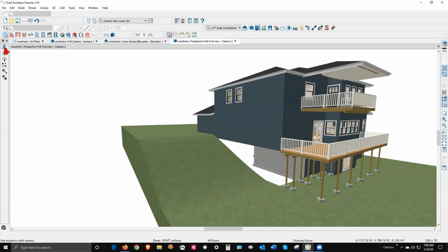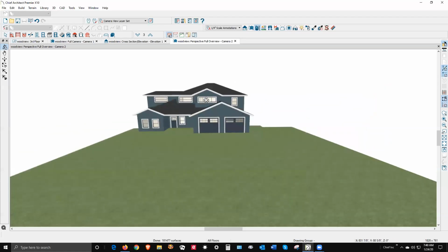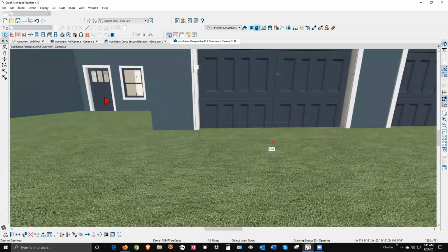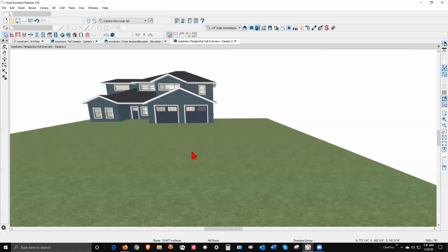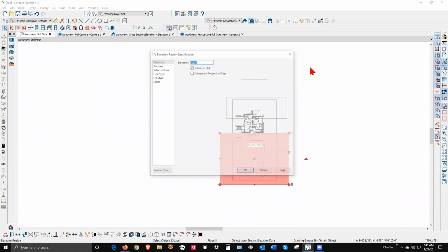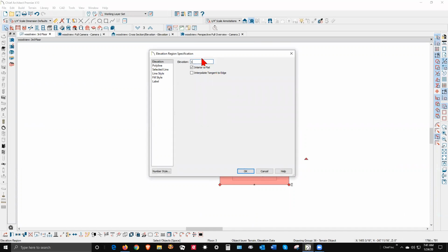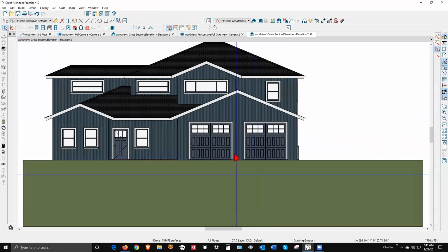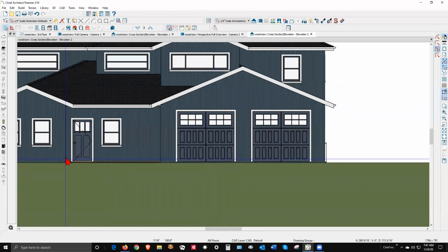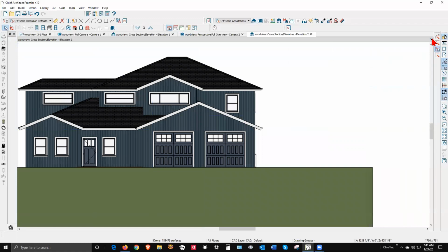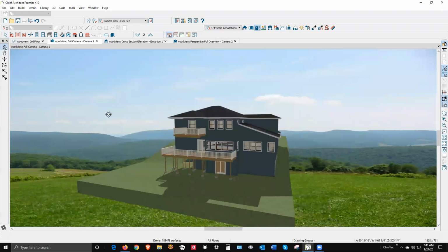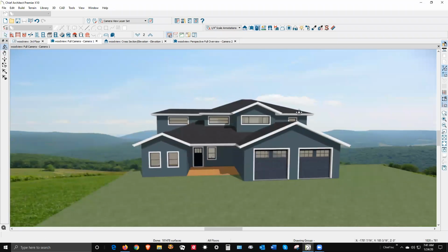Let's look at the front, because the back is workable now. The front's a little bit high. See, here's the garage doors are below grade, and this is below grade. So I missed my mark a bit. So it's not 120. Let's make it 108, and then check it. I'm going to go back to an elevation camera to evaluate. Okay, that's about right. I'm going to check it in the overview camera as well. That's the back. Yeah. I think we got a product now.